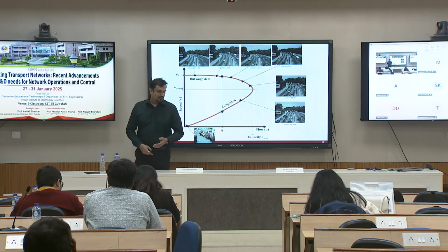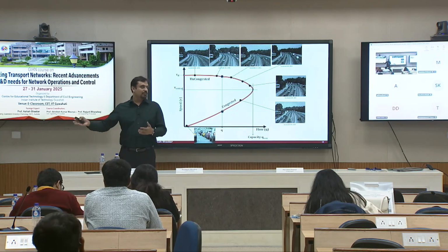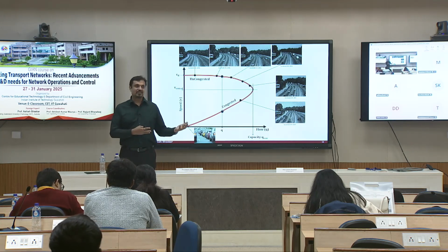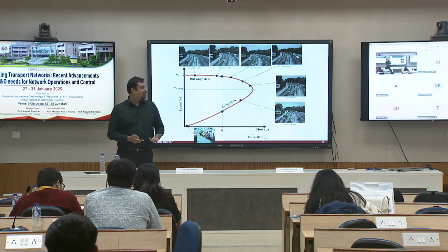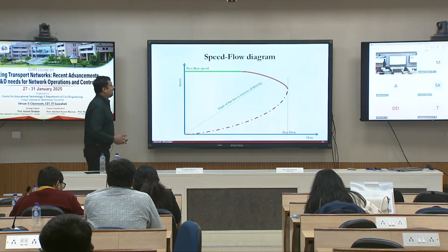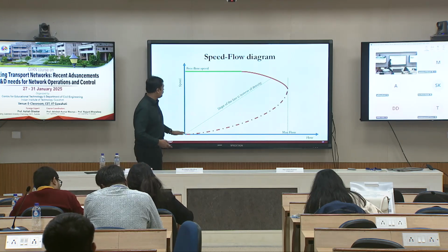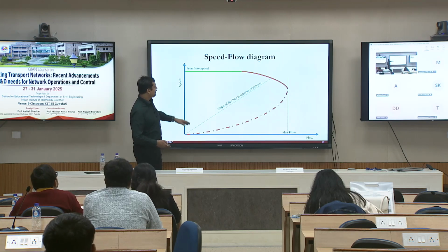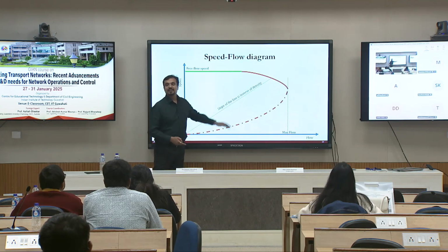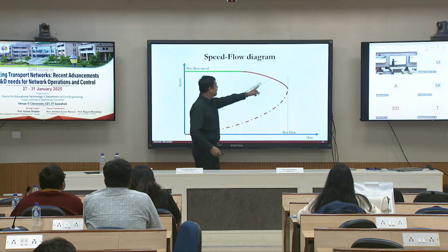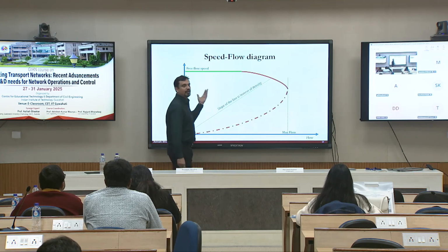Density, as was told in the previous lecture, is one of the good indicators for congestion, because this is something you feel, though we have seen that density is hard to measure. Another thing is the slope of the line joining the origin to the speed-flow diagram, which is the inverse of density. If you apply Q is equal to K times V, the slope of this line will have a gradient of the inverse of density.